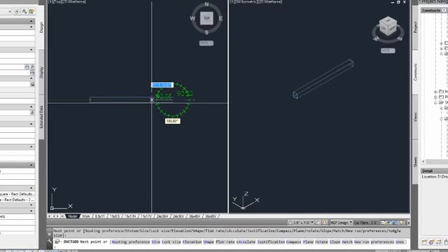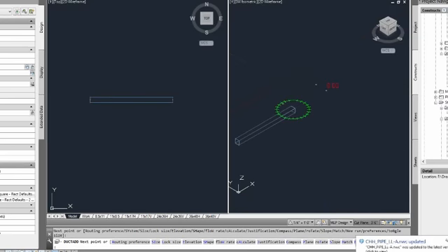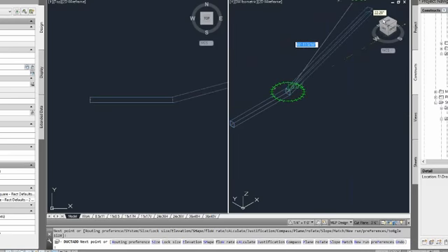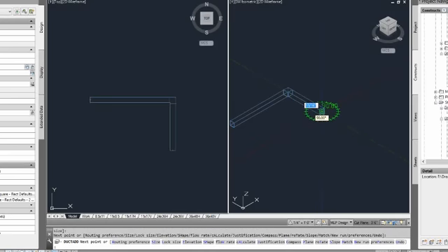Very powerful. But more importantly, when you're over here in a 3D view, it shows you the plane that you're currently drawing on. So currently I'm drawing in my top plane. If you look at the orientation of that compass versus the orientation of my view cube, you can see that I'm in the top plane. So when I go to turn my duct and put a piece in there, an elbow, it's always going to rotate that elbow in the top plane.